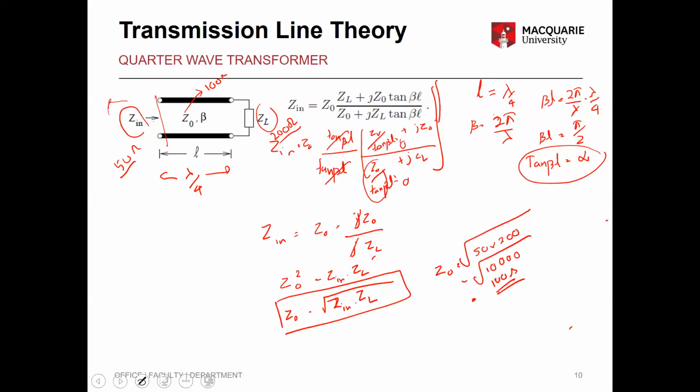This is a very important concept, and you'll notice that a lot of circuits will use that. A 50 ohm transmission line will have a certain width, and the 200 ohm delivered to the load will have a certain width, and then you'll notice there are quarter wave step transformers in most of the circuits, and that length is lambda by 4, and that width gives you 100 ohm.